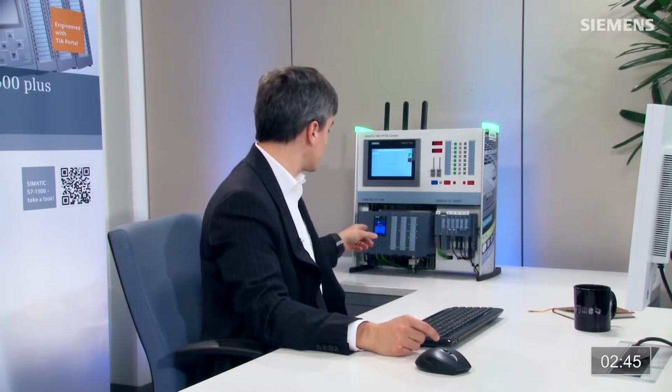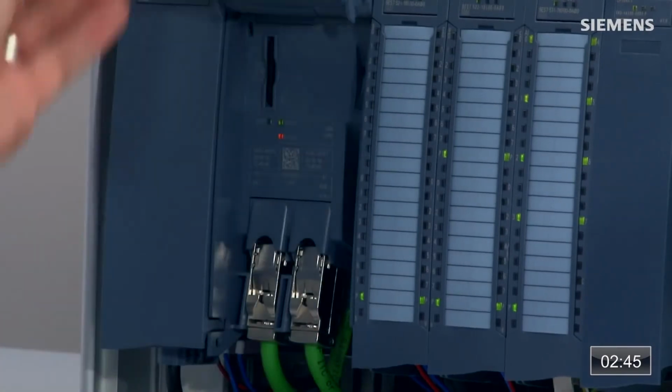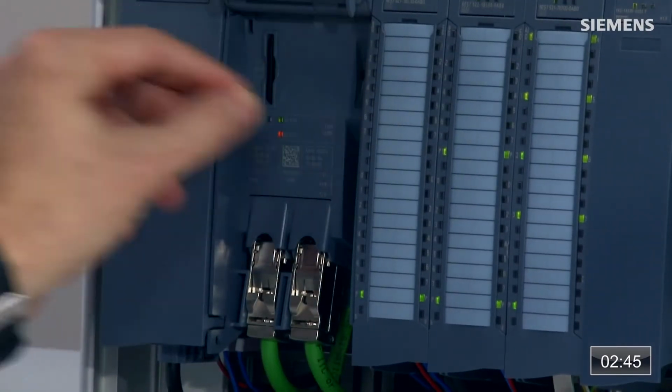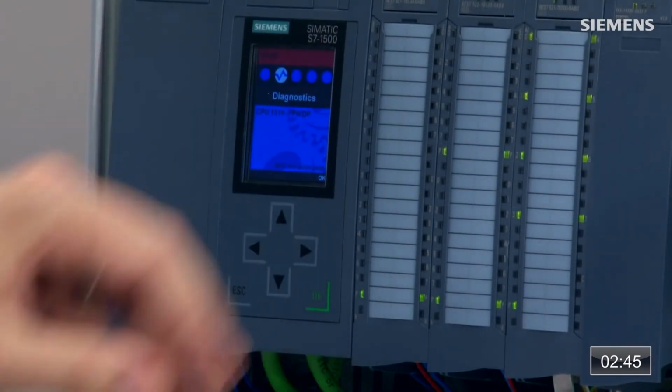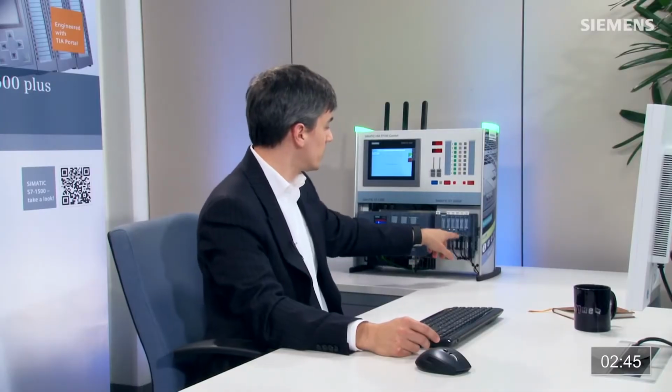So how about this actual display directly on the 1500 itself? Let me put the CPU in stop mode first. You can see it's clear in stop mode. If you remember, this analog card I'd actually turned to plus or minus 5 volt instead of plus or minus 10 volt. So I can actually generate a